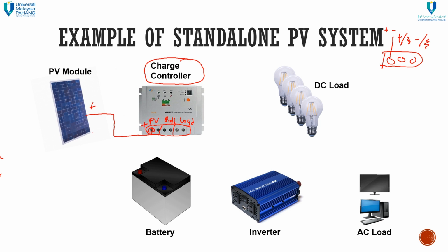Usually this is the plus. Okay, this is plus. Let's say we have the minus cable here, so you just connect it to the next segment, which is here, and this is the minus. Okay, in the middle, sometimes we have the blocking diodes here. Okay, blocking diode here, and sometimes we have fuse.